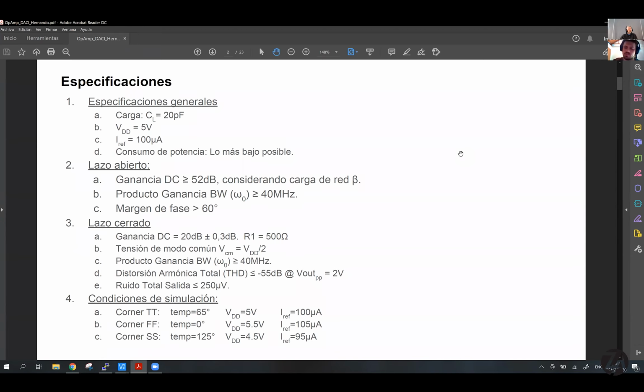I'm not sure if it's just something physical on the wafer, but maybe one transistor next to another might change a little bit how it works. So you have to test. It is good to test that your design will work in every possible combination of the functionality of the transistor. So in this op-amp design, I tested for all the possible corners. That's how it's called.